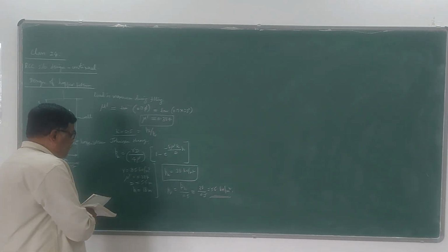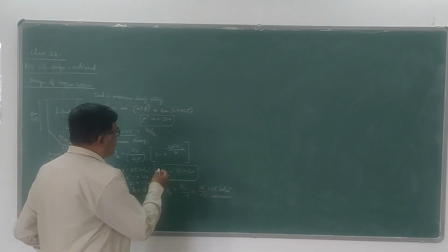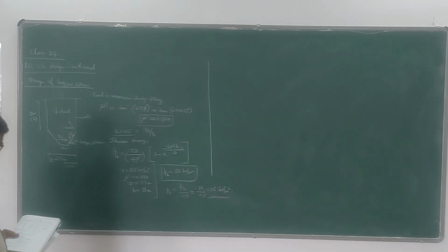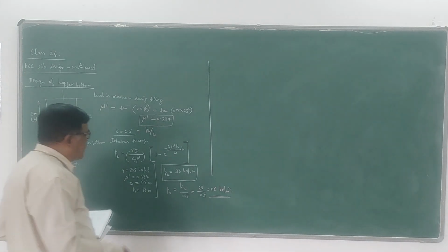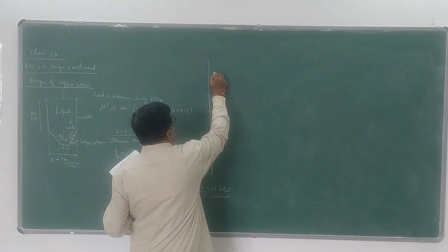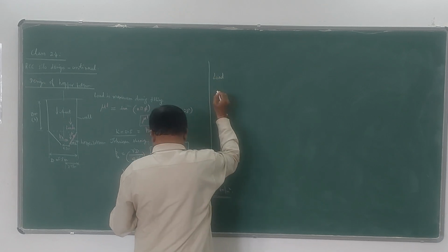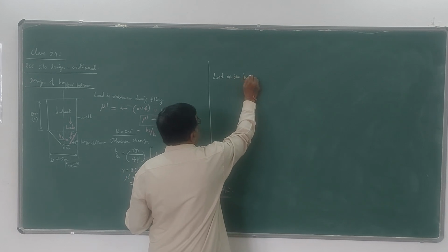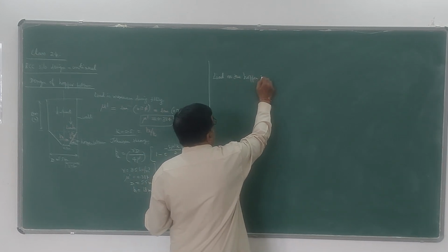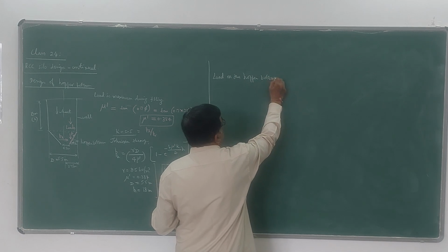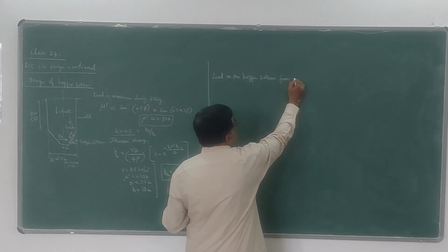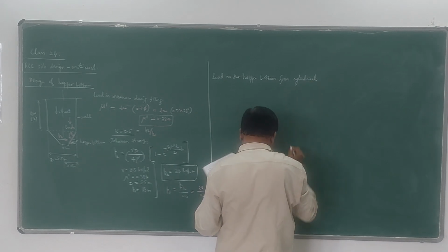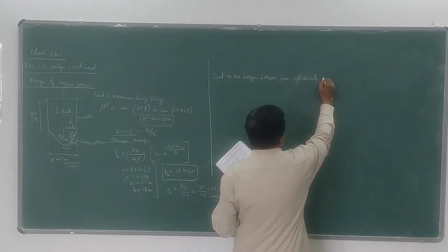So we can calculate the load now. From pressure we can calculate load by just multiplying by the area. As already told, there will be three loads: from the cylindrical portion, from the conical portion, and the self weight of the upper bottom.